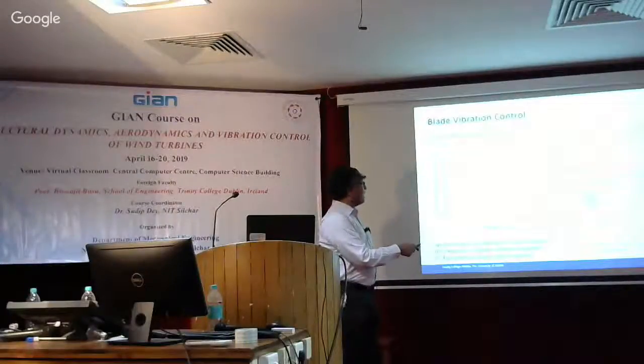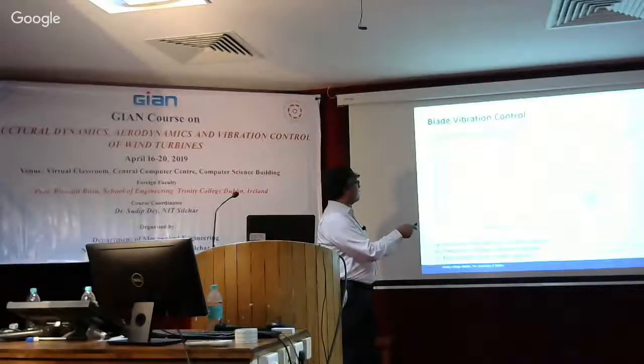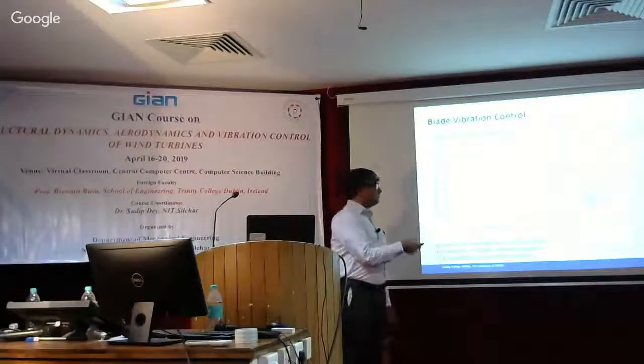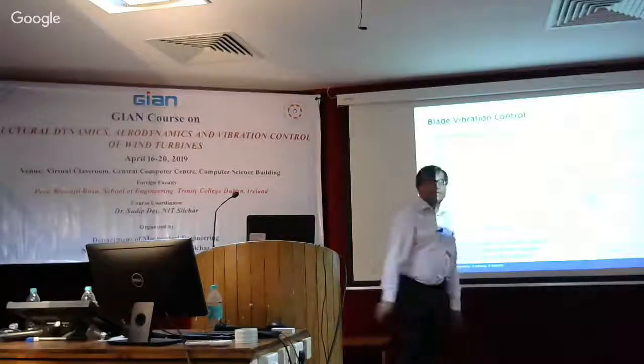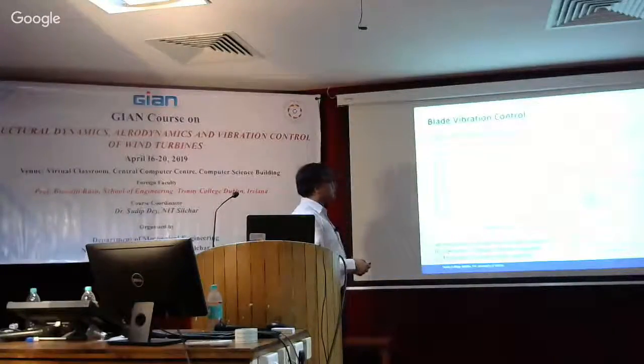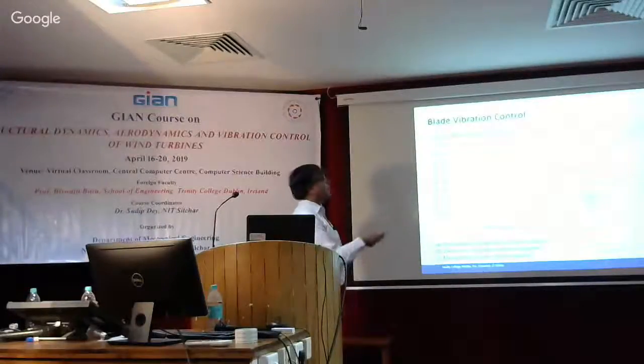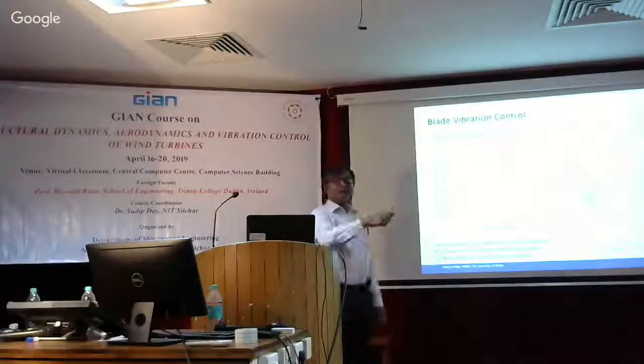So from pitch 4 to 10, or say pitch 4 to 8 degrees, you can see that there's a reduction from 40% to almost 65%. But that we can have if we keep the pitch at 4 degrees, but increase the active tendon load from this blue curve to the green curve over here. So the same amount of reduction is possible that we get from the pitch. So now we have the option of not activating the pitch, because the effect of the pitch in terms of loss of power is pretty clear over here. And the same applies for in-plane blade response. So you can see, because they're coupled, one will have an impact on the other.